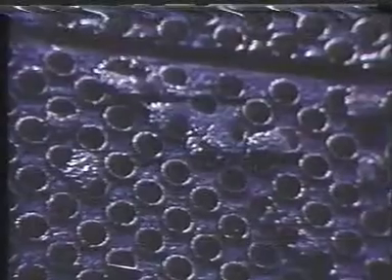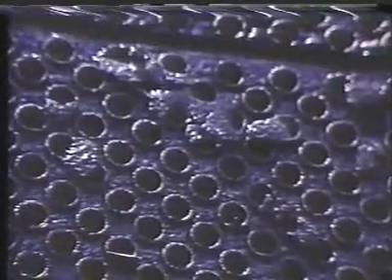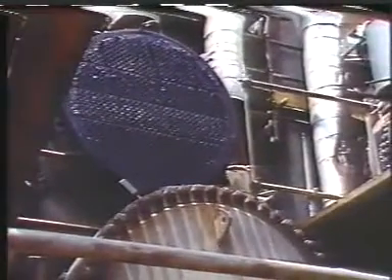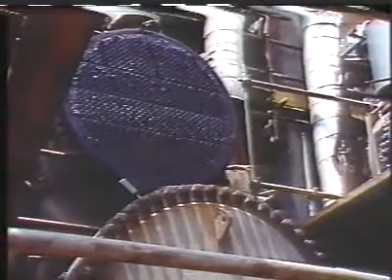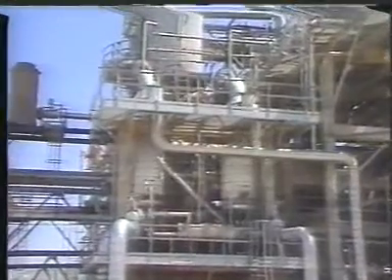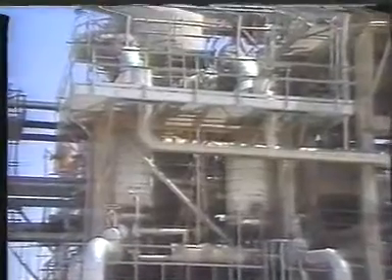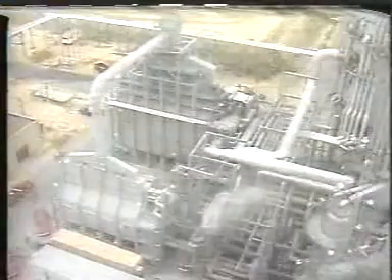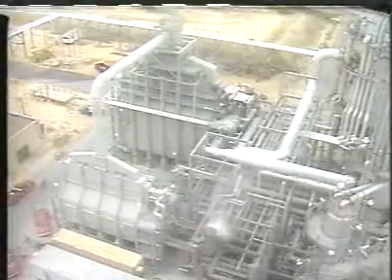A less severe but more common problem with overhead systems is fouling or scaling of condenser tubes. Deposits in the condenser tubes interfere with flow through the vessel and decrease the effectiveness of heat transfer from one fluid to another. Another situation that will cause a tower to operate abnormally is the loss of the heating medium to heat exchangers and reboilers, or the loss of fuel supply to furnaces.